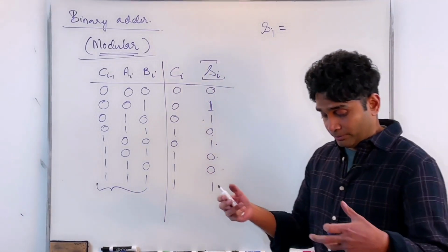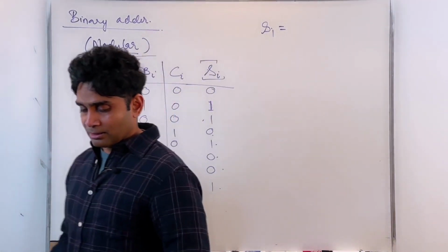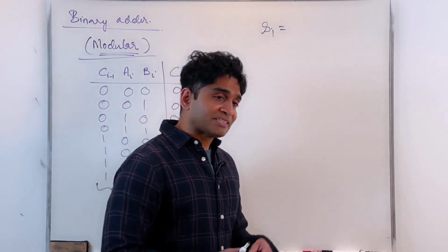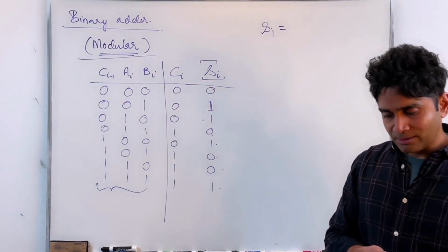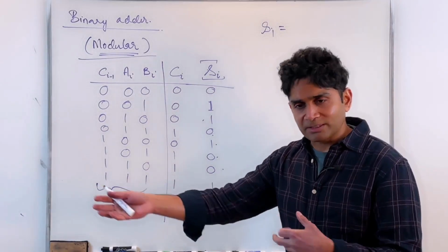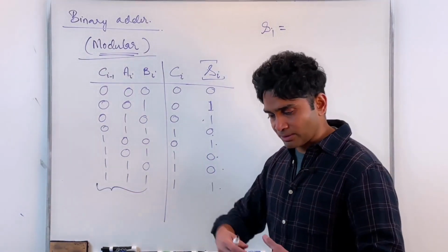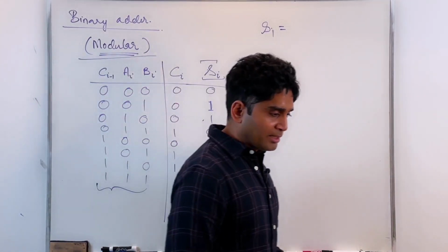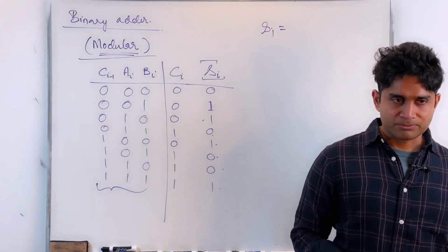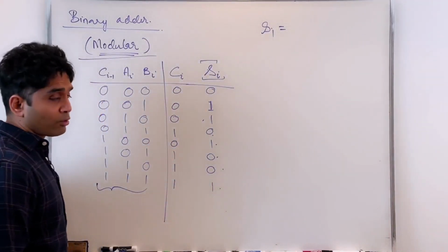And if you recall from just a few minutes back, I can extrapolate the same result for 8 bits. We have done it for 4 bits. The way to extrapolate that to 8 bits is basically XOR between the inputs. Just add more inputs and then XOR between the inputs, you get the 8-bit odd parity generator. In this case, it's just a 3-bit odd parity generator.